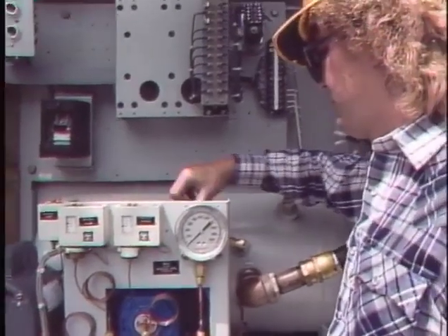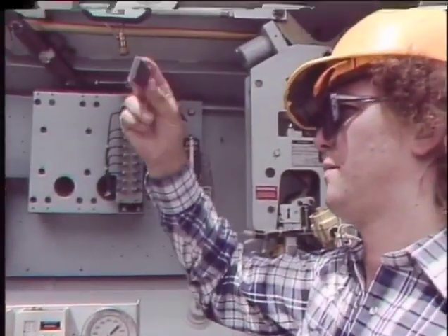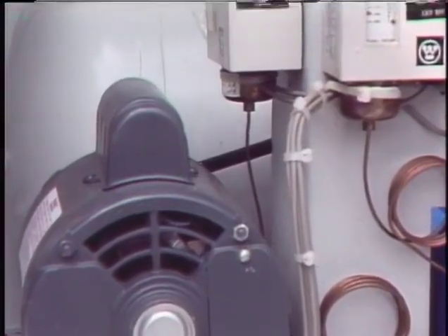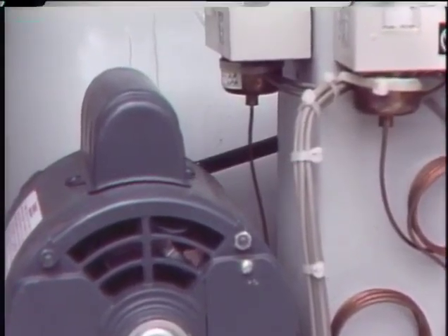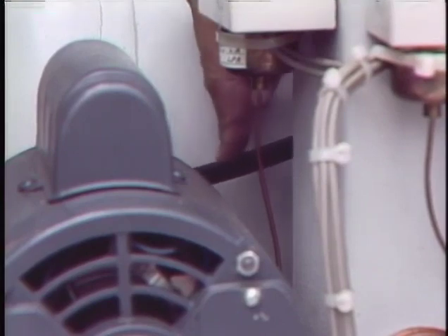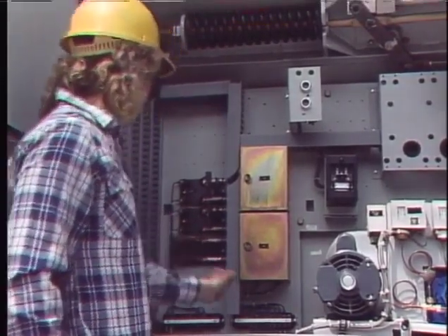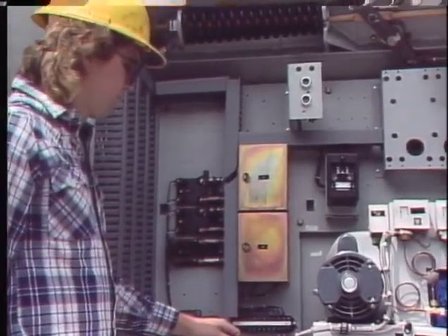The compressor air filter is inspected for dirt and is cleaned or replaced if necessary. If the compressor has a drive belt, it should be checked for signs of cracking or drying out and for proper tension. If the belt is in bad condition, it should be replaced. If the tension is off, it should be adjusted. After the compressor has been serviced, it can be energized so that it repressurizes the system.